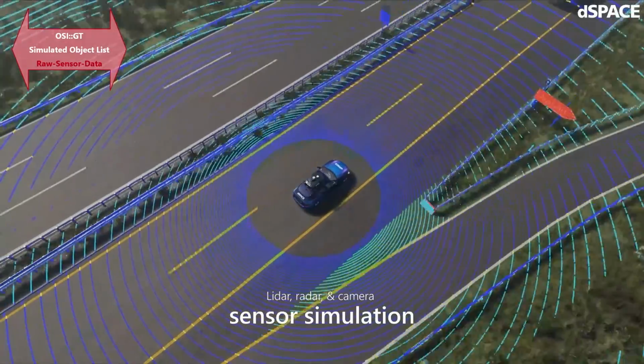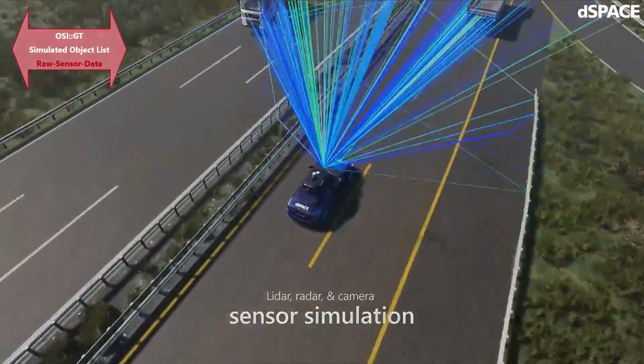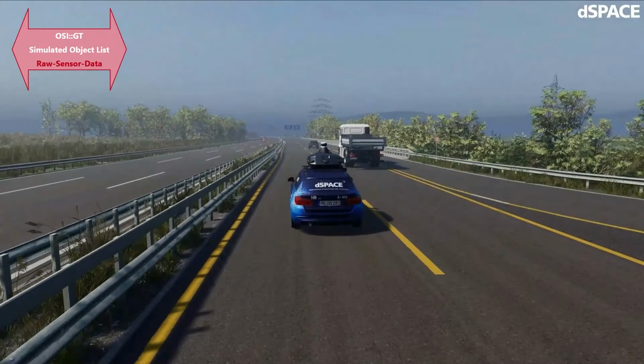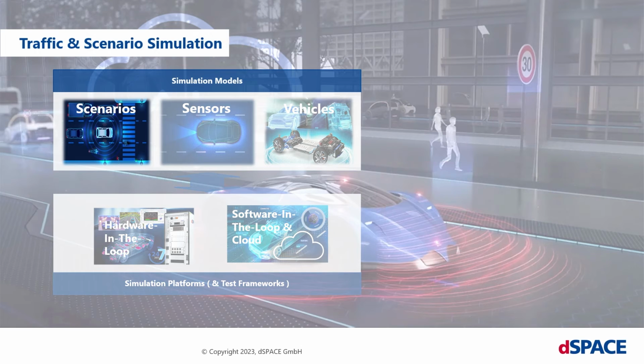And finally, our physics-based sensor simulation, AURELION, simulates sensor data on raw data level for camera, LiDAR, radar, and in the future also ultrasonic. Here we just talked about the generation of the required data for interfacing with the system under test by the model. dSPACE, of course, also provides sophisticated solutions for the required electrical interfaces in our hardware-in-the-loop simulators, ensuring synchronicity while also mastering high bandwidths.